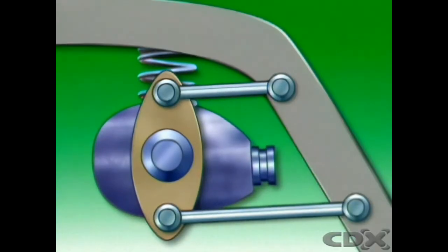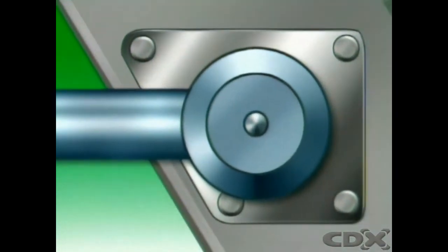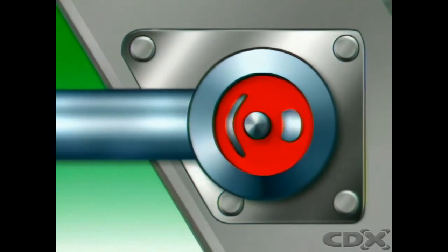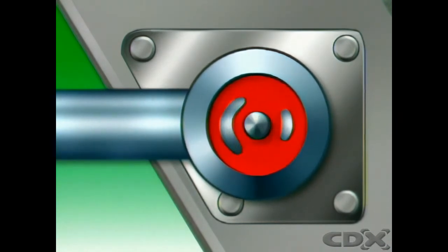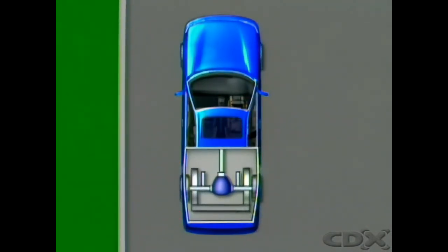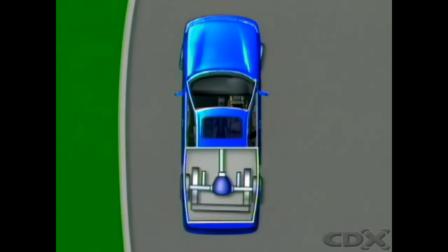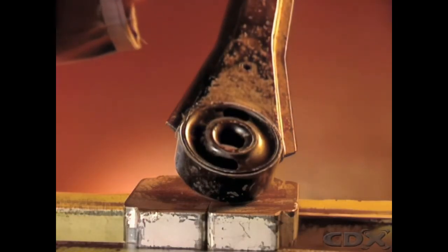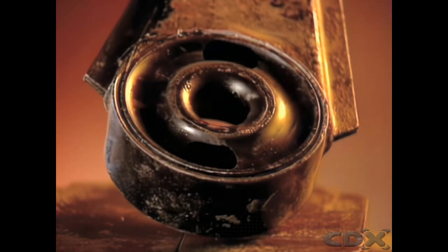In control arm applications, particularly at the rear of a vehicle, the rubber bushing may be molded with a voided section. This is known as a compliance bushing because it allows the unit or component to comply with a controlled amount of movement in the direction of the void. This movement relative to the vehicle frame allows compliance or deflection steer of the road wheels when cornering. Since this influences the steering behavior of the vehicle, it is very important that the voided section is in its correct relative position.